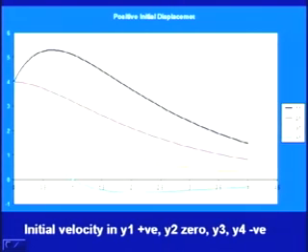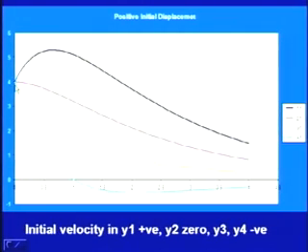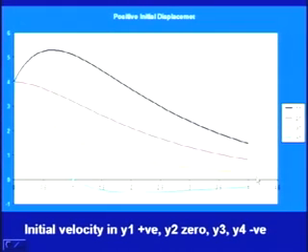When the initial velocity is negative, that is, the initial velocity is upwards, then we could have two cases. One is that it goes down like this and then dies down, the displacement coming to 0. Or it may happen that it comes to 0 and then goes to the negative side, that is, the motion is upwards, but again it will come back and go to 0. So if damping is present, ultimately our motion would stop and after some time we would go to 0 displacement.